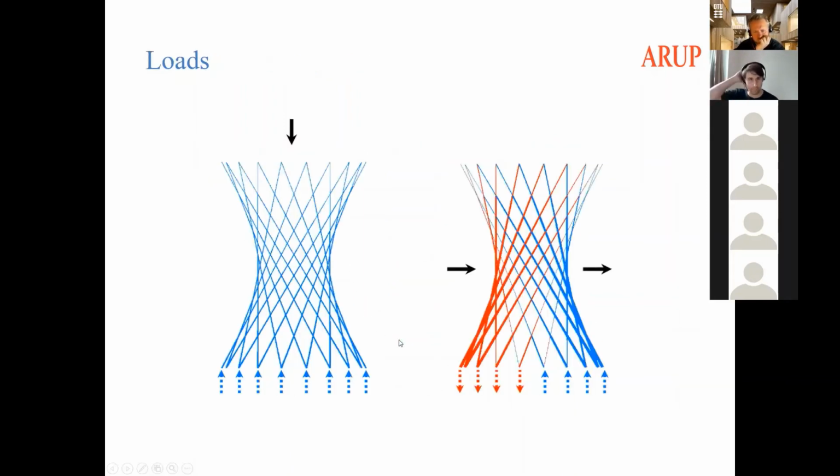Just to start off, it's always nice to look at the global loads. Not surprisingly, when we have the tower under vertical load only, self-weight for example, we get full compression in the tower. And when we get a horizontal load, like wind load coming from the left, we get tension on the left side of the structure and compression on the right side.